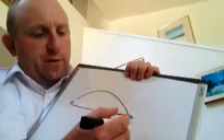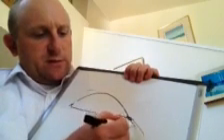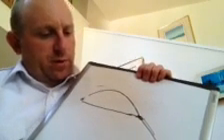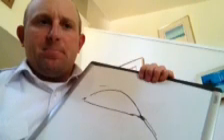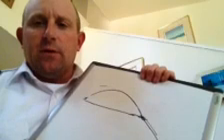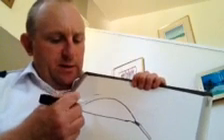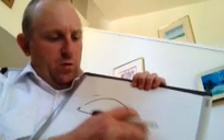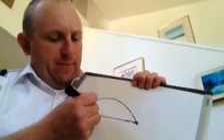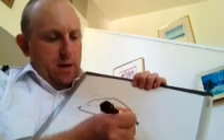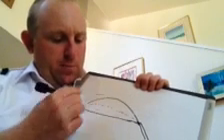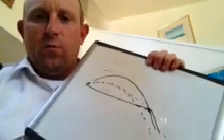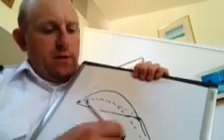In general, flight controls are hinged devices on the trailing edge of our airfoils. Our airfoils would include our horizontal stabilizer, our vertical stabilizer, and our wings. What that does is it takes the normal camber, our average camber line, and if we add to it, we're creating much more camber, more curvature, so that equals more lift. So that's the premise that all these different airfoils work on.